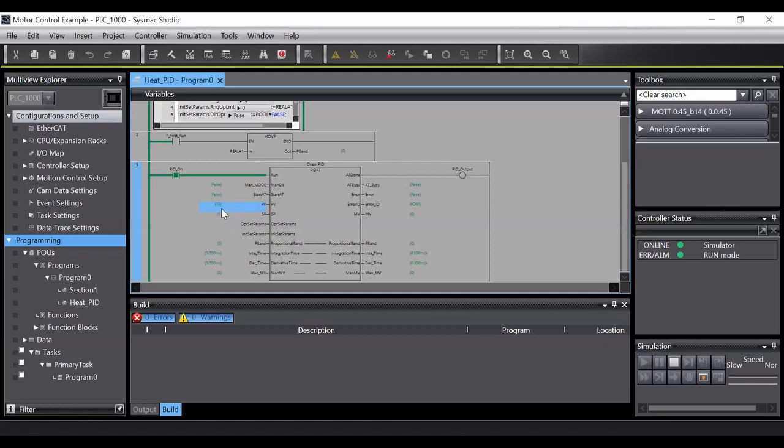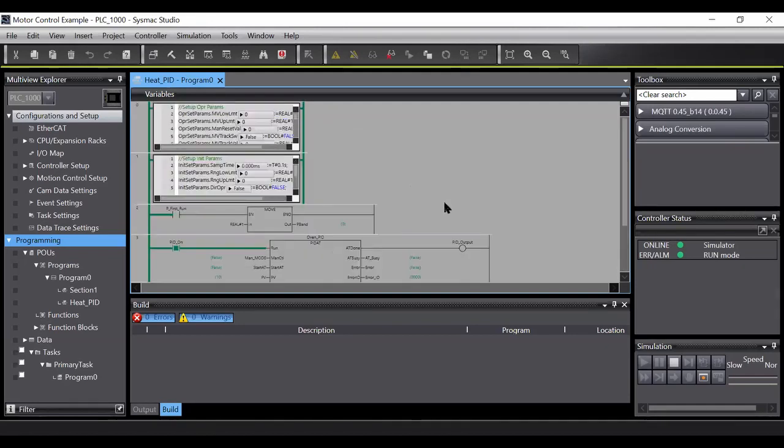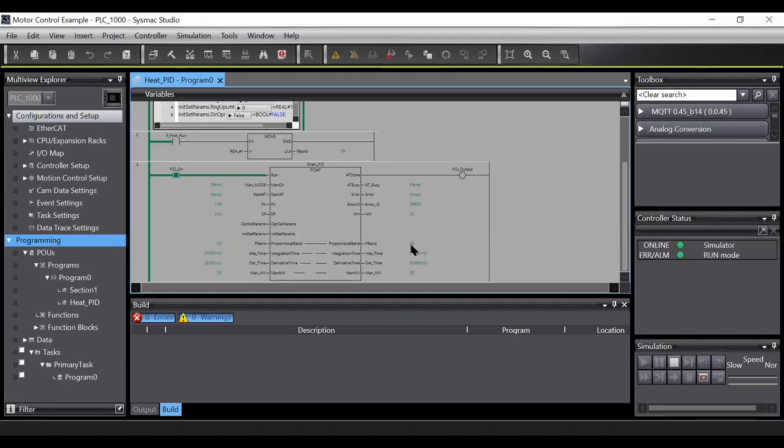I see. Okay. So you can go ahead and give it a set point. You can leave it at 10, it's fine. Just make your set point higher than 10. Okay, so you should have some output now, but you don't. Your P band is 0. So just change that to a 1.